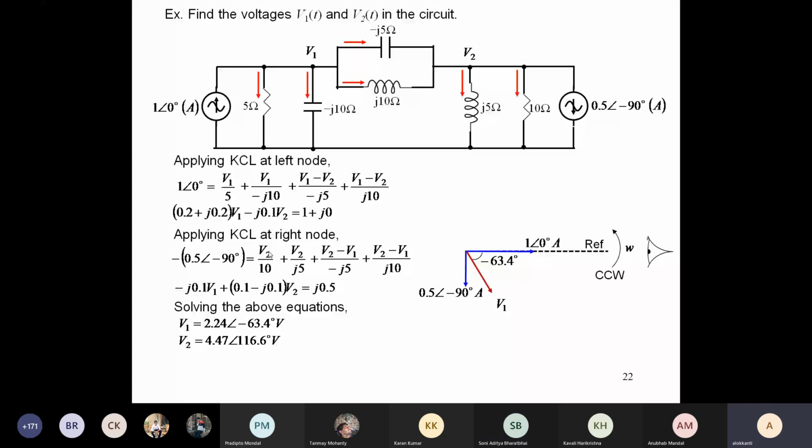And obviously you have to write that it is voltage, because the physical quantity is voltage. That has to be written. So where is 116 degree? It is 180 degree out of phase with V1. Correct. So you see, 116 degree is just 180 degree away from minus 63 degree, so it is obviously in the second quadrant. So V2 is lying here.